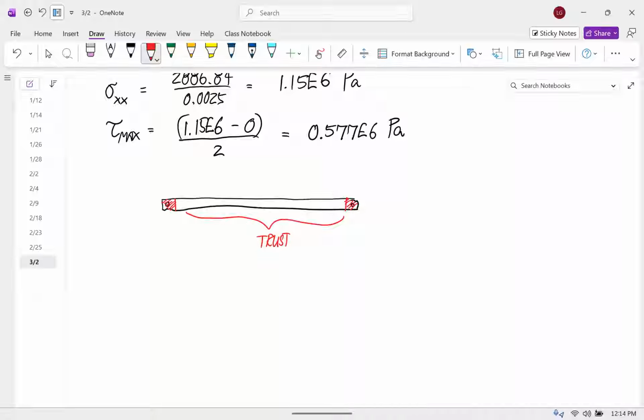Any questions about that one? On the hinge or whatever, then we can trust it. We could trust it all the way if what was happening was really a uniform distributed load at the ends. So that's what we're always assuming. But since these are kind of concentrated forces just at those little holes, there's going to be all sorts of weird stresses right around those holes.